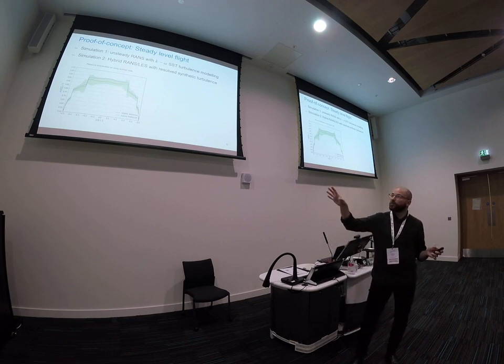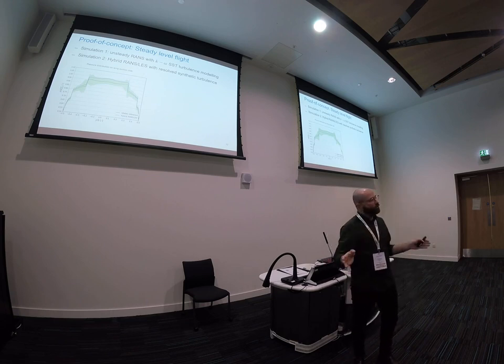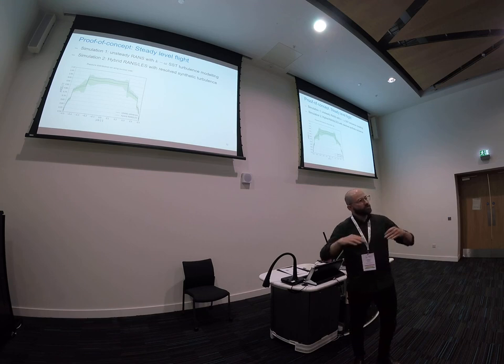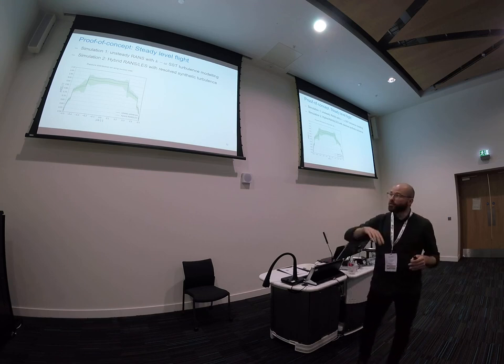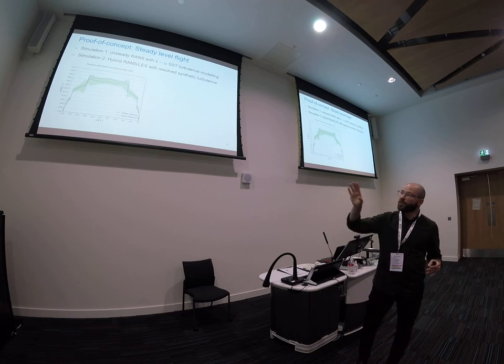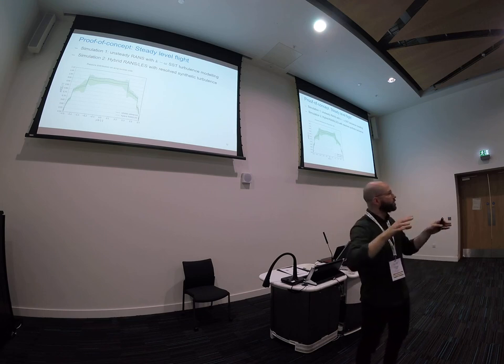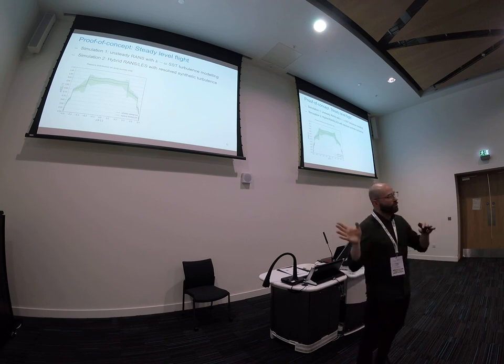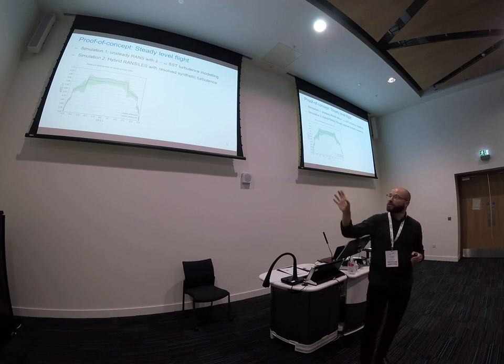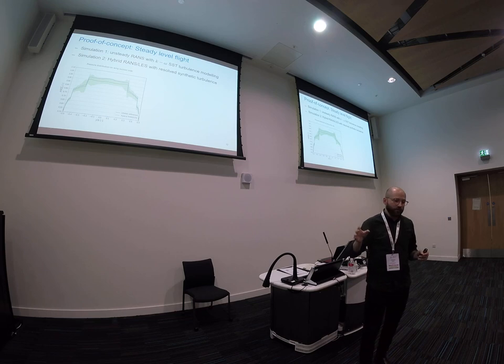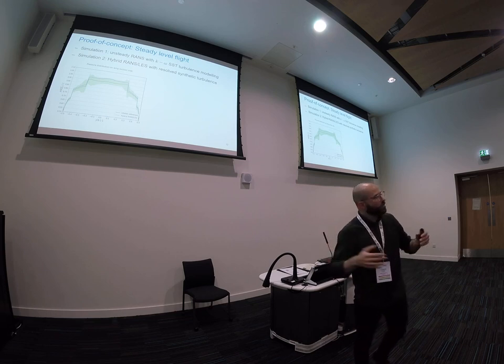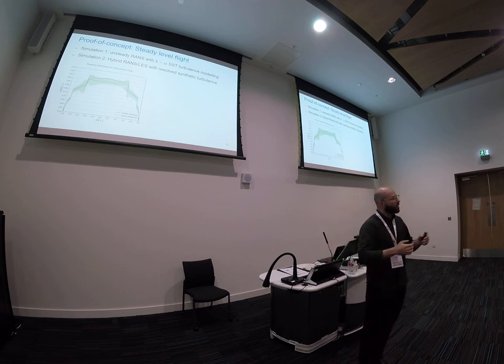So the plot on the left shows you the pressure distribution on the suction side of the wing, so on the upper side of the wing, the pressure distribution that is then normalized with the reference pressure distribution from the RANS simulation. So what we can see in blue, we show the pressure distribution for the RANS simulation, and in green for the hybrid RANS-LES simulation. And what we're happy to see is that with this hybrid RANS-LES simulation, we're able to capture the fluctuations of the forces.